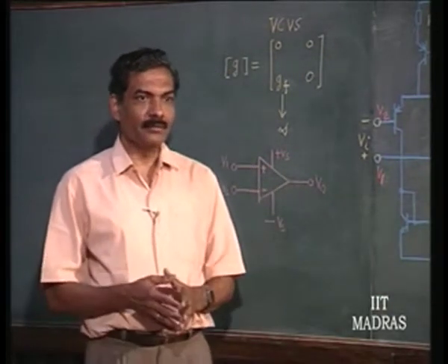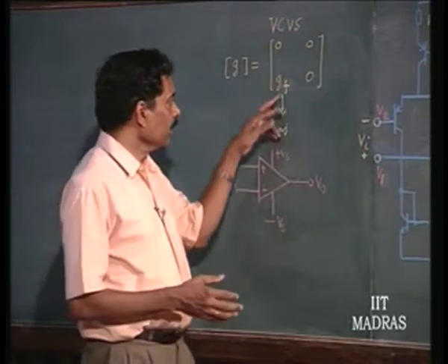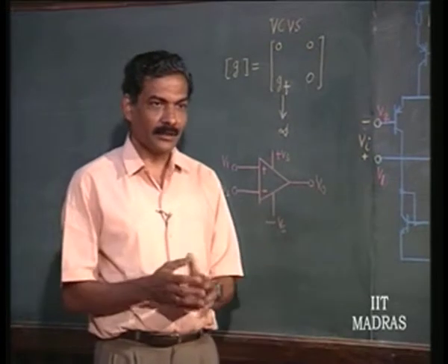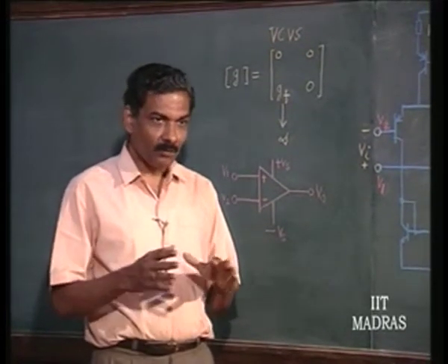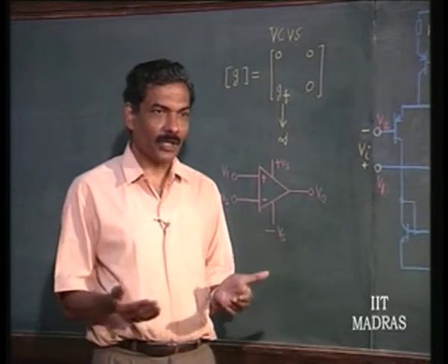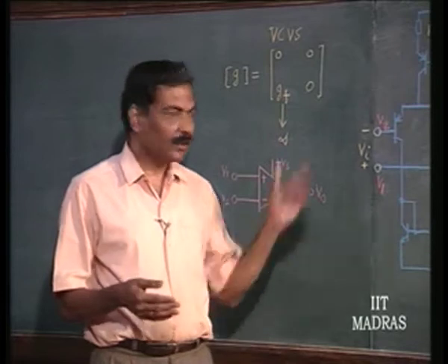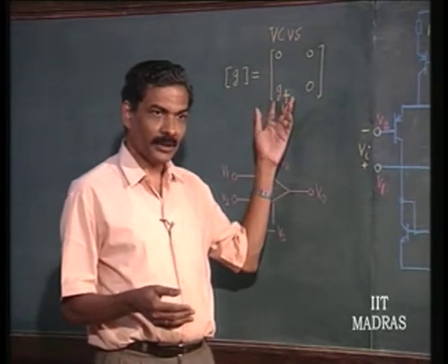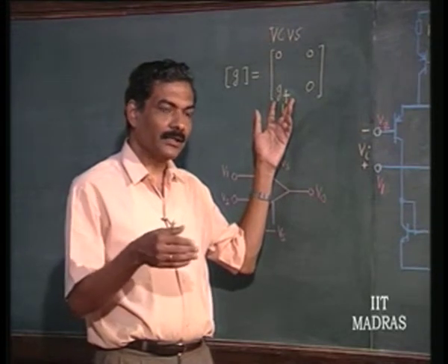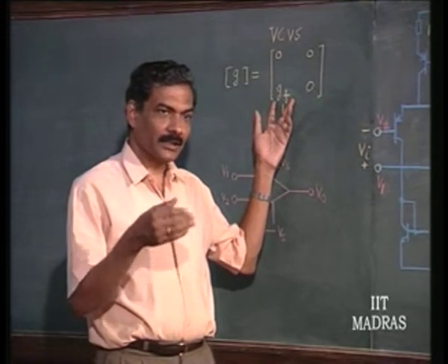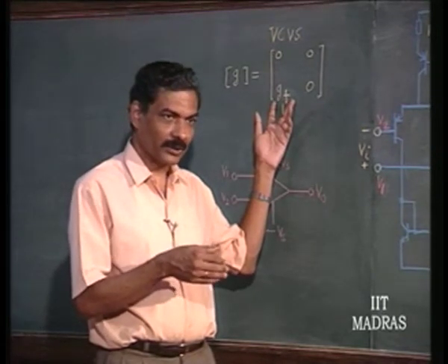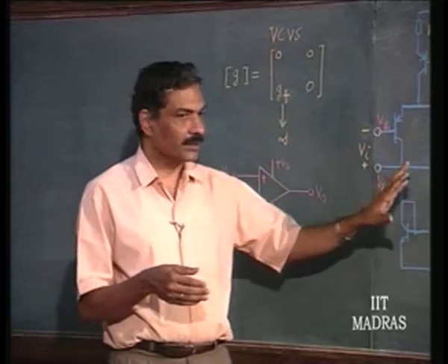We could have obviously improved this GF further and decrease this further by cascading more stages, but that will complicate the stage in terms of causing the state to have more number of time constants, which will determine the open loop, okay, transfer parameter, and therefore then result in frequency instability problems when used under negative feedback situations. That is why we have frozen the number of stages to 3.